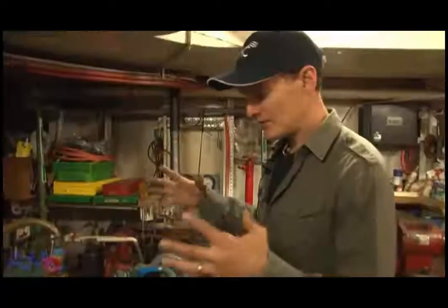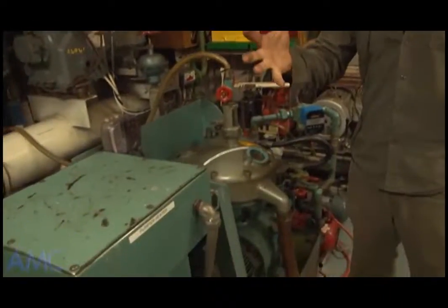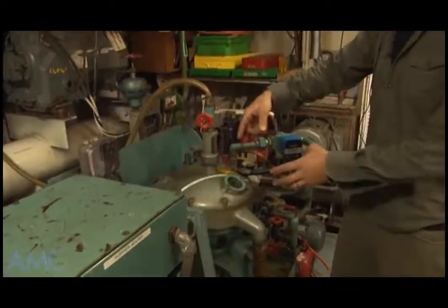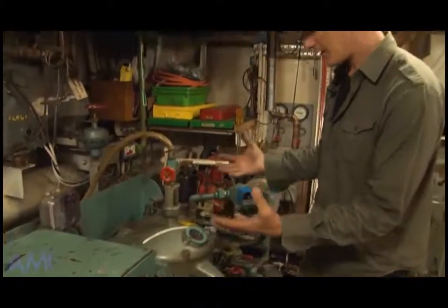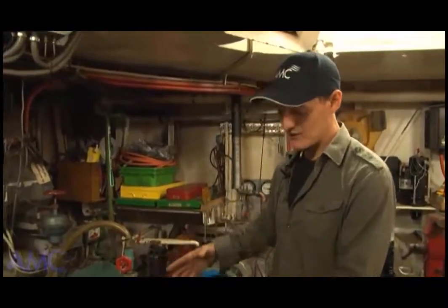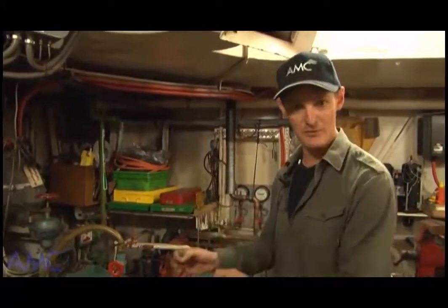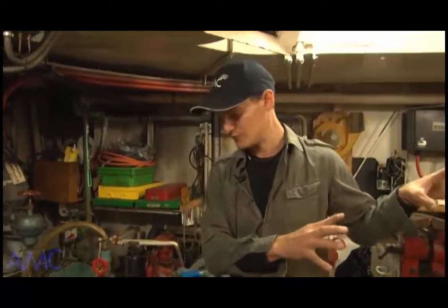Generally, we'll have a look at our purifier and our day tank in more detail. Our diesel oil purifier here: with our purifier we're able to take suction from our bunker tanks and put it through our centrifuge, or our purifier. This will rotate at high speed, remove any water contamination and any particle contamination, and it will be pumped from here up to our day tank as nice clean fuel.